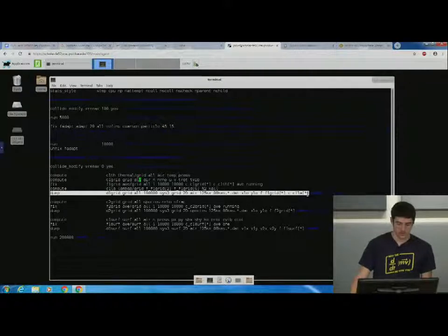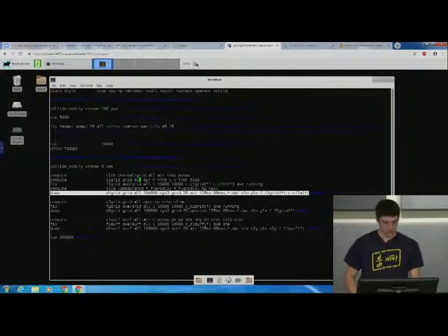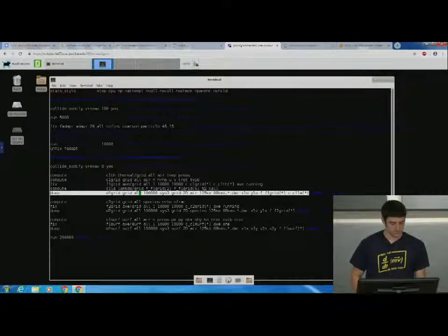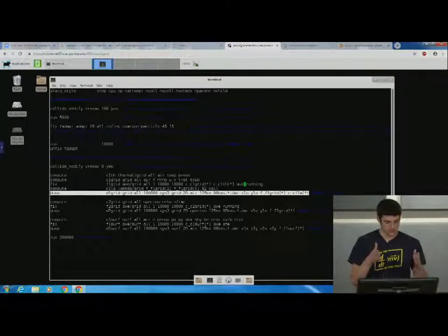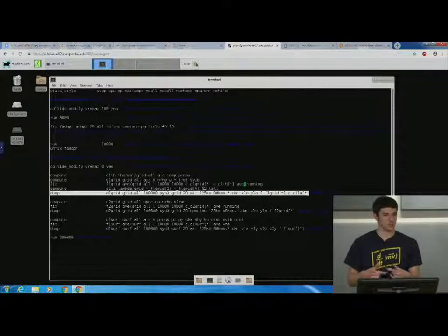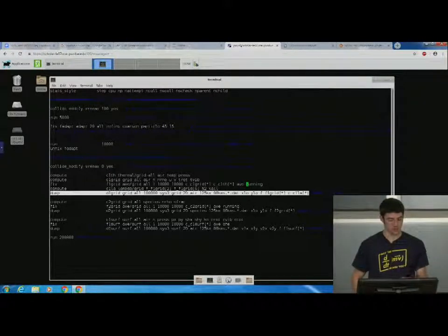Then after you compute it, this command comes in where you actually need to dump the file so that you can actually see it, plot it, things like that. So here I'm doing every. One thing I should mention about this fix command is that you have to average, and either you can average over single steps, so basically one time, or have a running average. In most cases, a running average is better, but depending, sometimes you just want a single output. So this will be one or running for that.